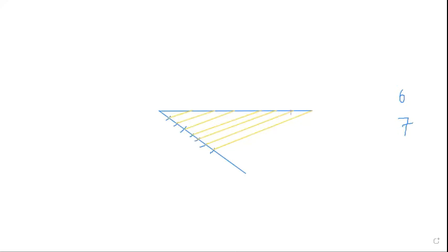So in this way, you can divide any length of line into any number of divisions. This is basically called the general method for line division. So this is the way you can divide the line. In your problem, if suppose 40 millimeter is divided in 8 parts, each part will be 5 millimeter easily. But if it is given 9 equal parts, in this way you can divide in general.